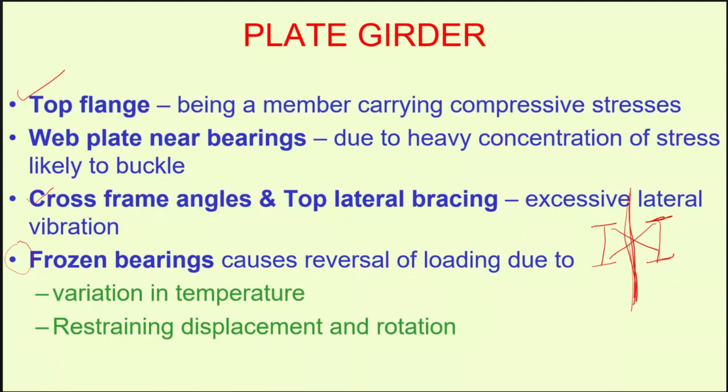And when the end is rotating, the bearing of the girder or the bottom flange needs to move from its mid position, and if it is not permitted to move or deflect, then it will attract some eccentric forces and thereby induce bending stresses in the plate girders.